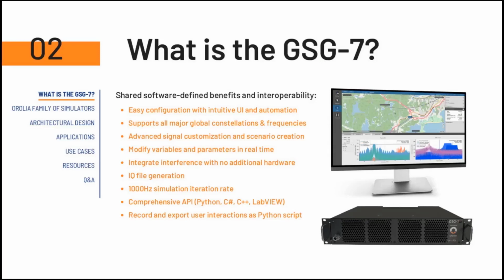the interface to the Skydel simulator. So with this API, it's very, very simple in a few clicks to record all the actions in the interface, and then record all these actions in a Python script, for example, and then replay it in an automated script. So it's really, really simple to interface with Skydel, automate Skydel, and do very complex scenarios in Python or other programming languages.